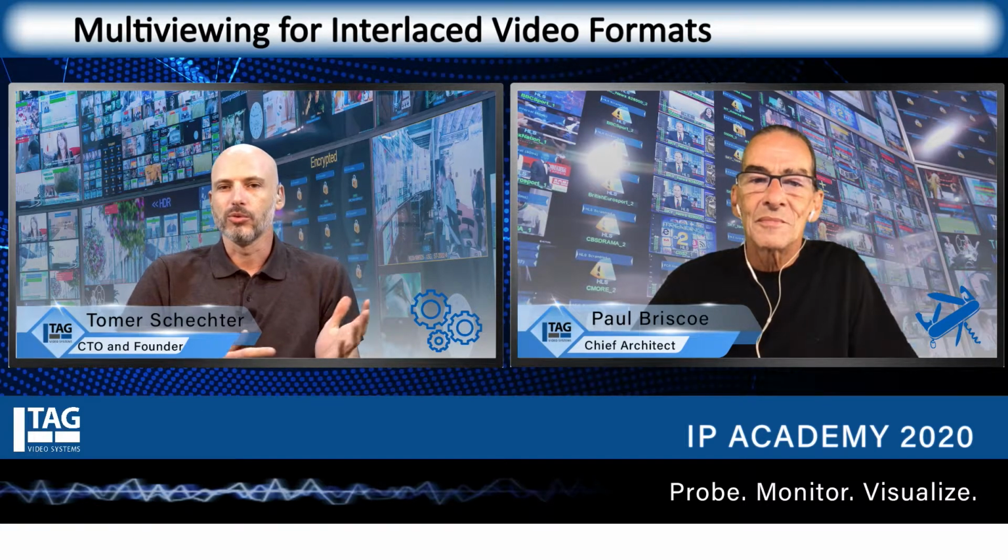Yeah. So film is 24 frames per second progressive scanned. And when you're converting it to interlace format for the American sides, then it's 29.97. It's really 60 fields per second. So it's exactly 2.5 times the original frame rate. So there is an algorithm for how to create the interlaced format from these 24 frames. It's called pull down, 2:3 pull down, something like that. I don't remember the term.